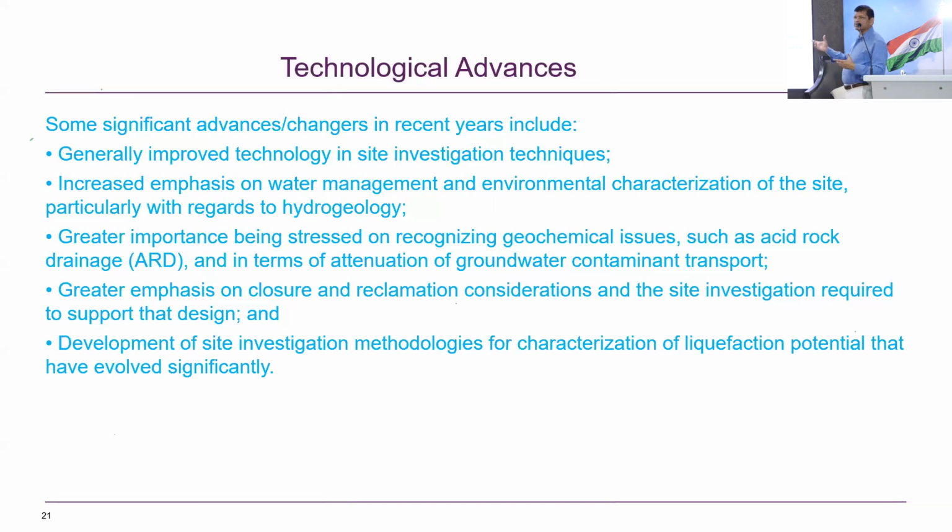Increased improved technology, like the cone penetration test. These are new. Before 2000, very few sites had it, but in the US, Australia and Canada, currently every site does CPT. We do repeated CPT every 4 years as we raise the dam.